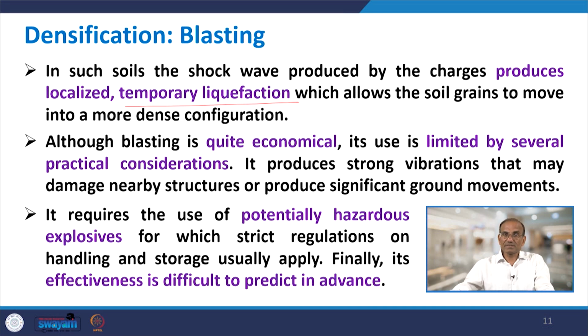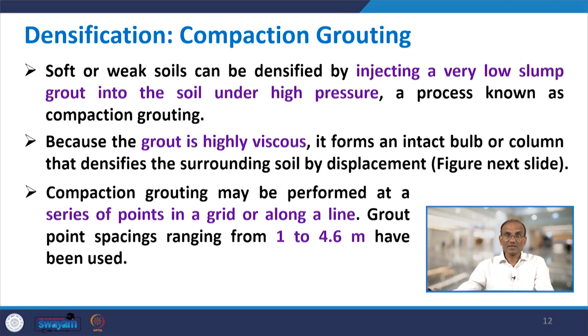Although blasting is quite economical, its use is limited by several practical considerations. It produces strong vibrations that may damage nearby structures or produce significant ground movements, and that is why it cannot be used near existing buildings or structures. It also requires the use of potentially hazardous explosive, for which strict regulations on handling and storage usually apply. Finally, its effectiveness is difficult to predict in advance, because it will depend on your type of soil, and particularly it may not be effective for partially saturated soils.